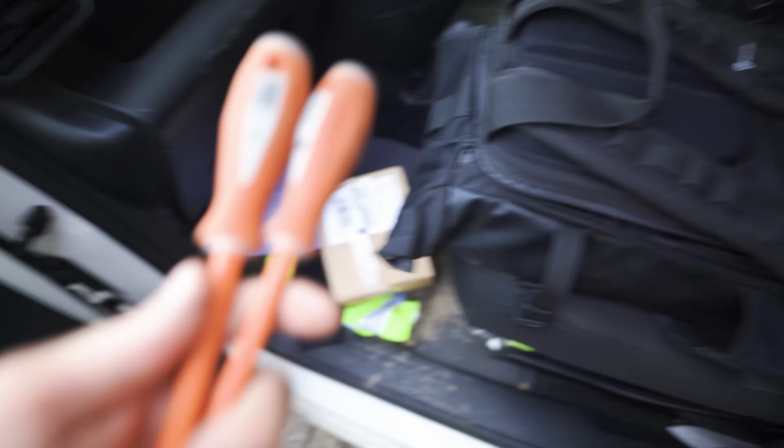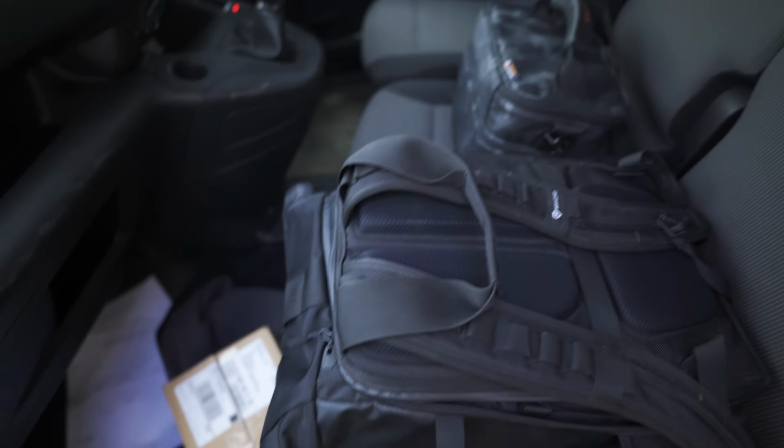What I'm going to do now is have some lunch briefly, and then I've got a new lunchbox actually, which I'm sadly excited to show you guys. And then I'm going to, apart from the one that I think's the issue, connect all the lampposts up in probably sets of 3. Connect 3 up, come back, test, all sweet, connect 3 up, because what I don't want to do is connect them all back up and there's a separate fault that I've then reintroduced and then I don't know which one it is. So I just want to do a couple at a time, and then I can again pinpoint any issues to a rough area, and then once they're all connected back up, bar the one that I think's the offending one, the broken one, I'm going to try to get the circuit back on, basically. Chuck everything on there for now.